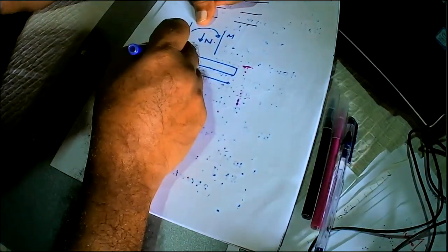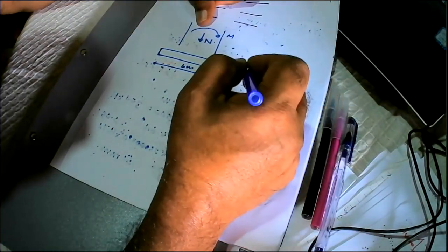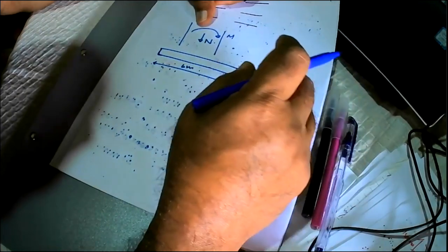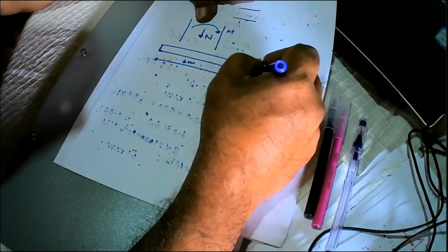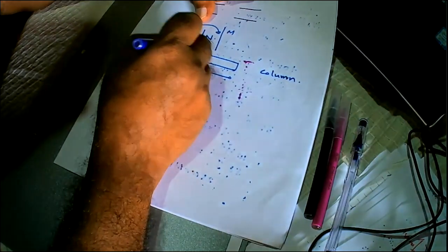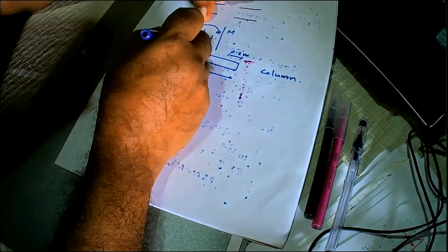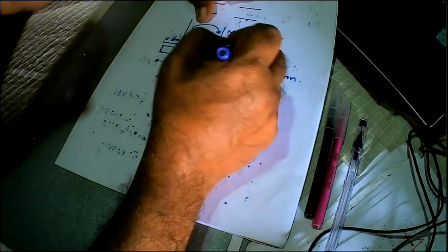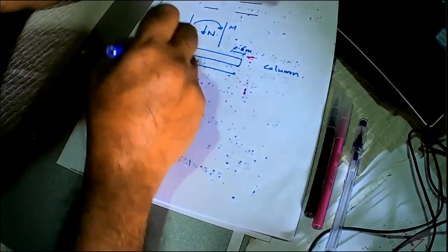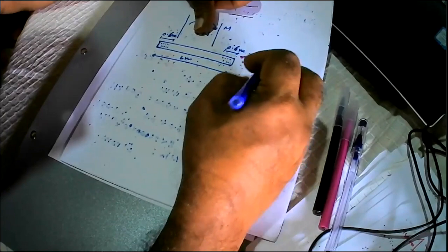there are two ways of finding the reinforcement. If there is no significant out of plane moment, then we can consider this as a column. And then, say, the corner 0.5 meters is going to be, say, 0.6 meters. Corner 0.6 meters, we'll have a concentration of reinforcement as in a column. And this is going to behave as a column.